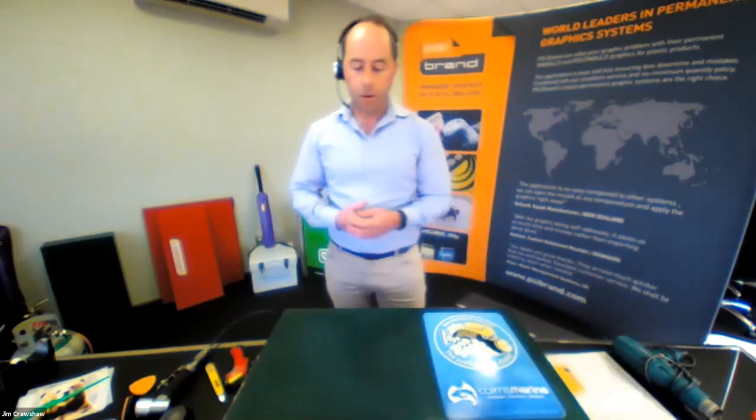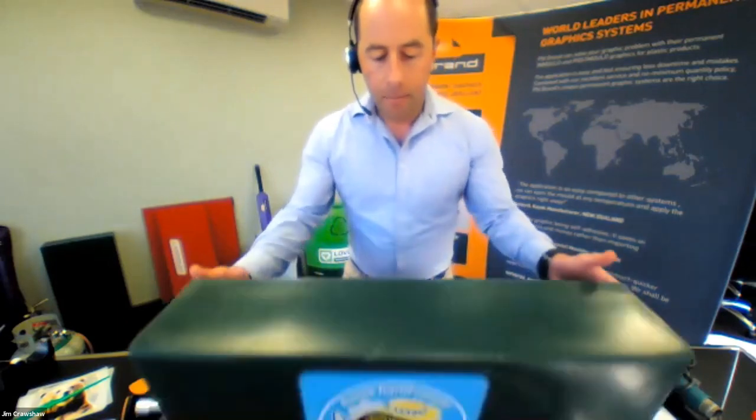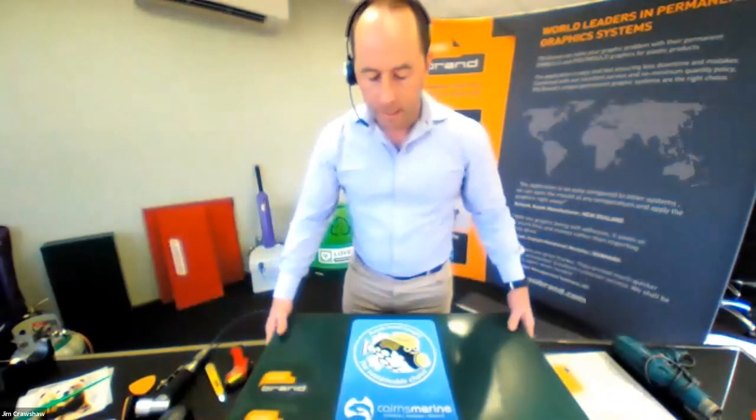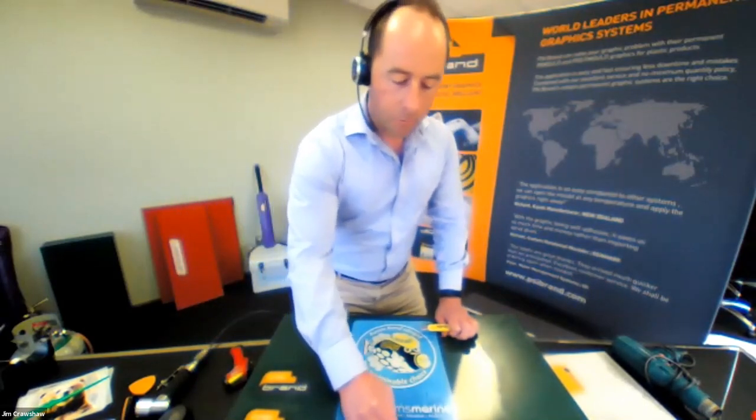What we suggest you do when you run your first molding tests is do some adhesion tests. What I've done is I've molded one yesterday just to show you what we do when we do an adhesion test. Typically you can do a fingernail test, which is just picking as hard as you can at the edge of the graphic. It's a really good indication. If you can pull your finger across and peel the graphic up, obviously we haven't gone hot enough. Always perform this test once the graphic is fully cooled.